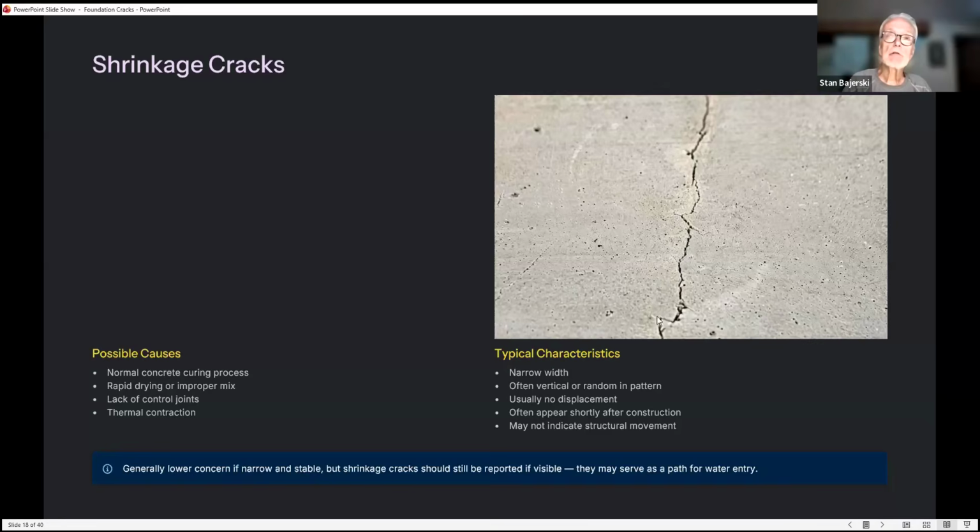You may not be comfortable with those cracks, even though they may not be big issues. You have to be comfortable making the call by knowing the characteristics, and you can develop a language, especially if it's newer construction, where you may have to watch it for a while because it's new and these are normal characteristics of concrete after it's poured. You don't have any idea who poured that concrete, how it was done, or how it was cured.